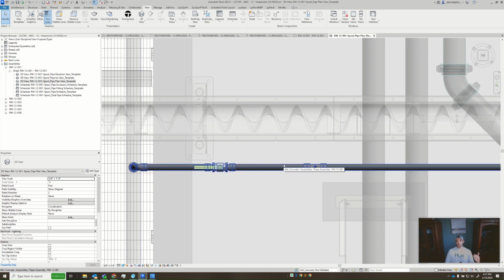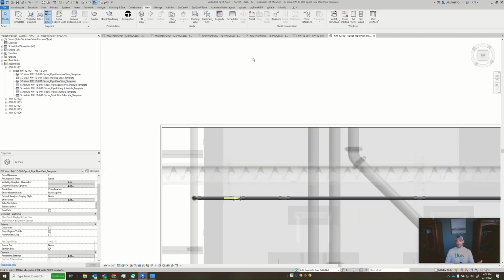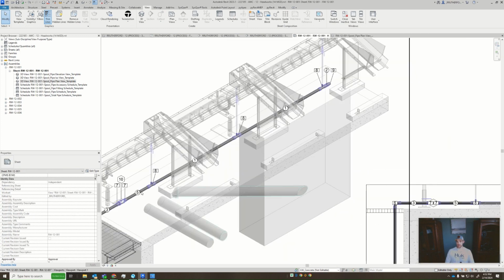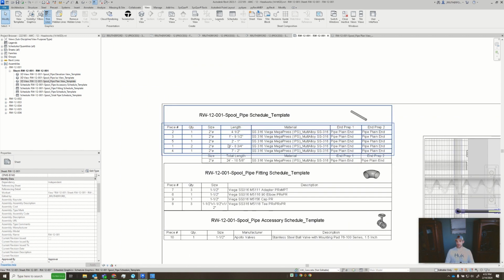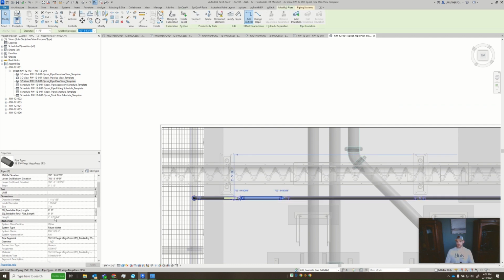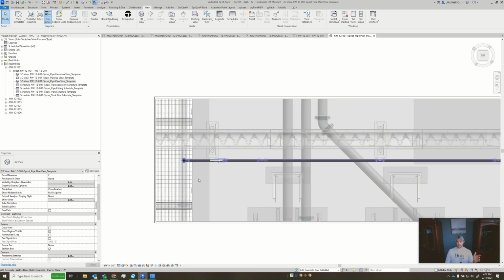Now, when we create these bill of materials, these particular elements do have a length. And in that bill of materials, if for instance this number, which we can find out here, this element number 5, for instance, has a length of 2'1". Now, as we saw when I clicked on that element here, it's actually 2 foot and 57/64 of an inch. So much more detailed here, but as far as the crew is concerned, they do not need anything more than a 16th. That is the greatest dimension I'll give them, is up to a 16th. Sometimes even an 1/8 is more than they need.